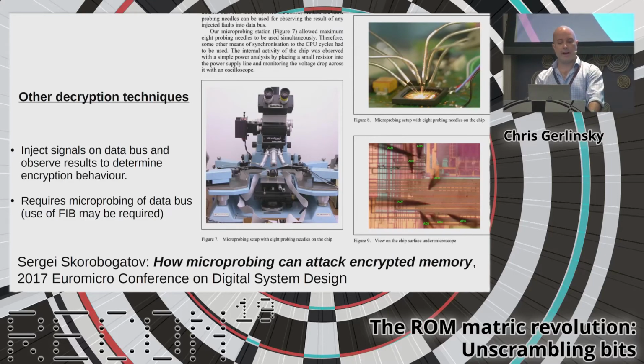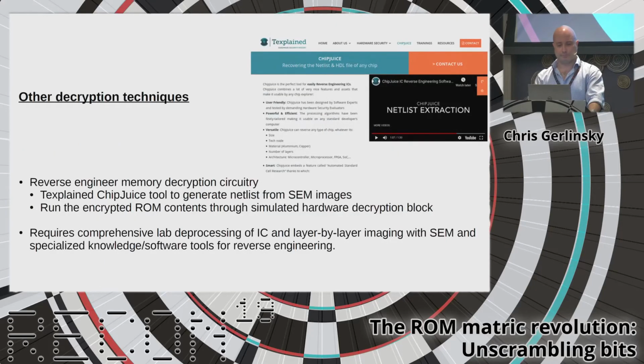This does require actually microprobing of the data bus on the chip that they used. They were able to connect directly with needles. You might need a focused ion beam or something if you're on a smaller technology chip.